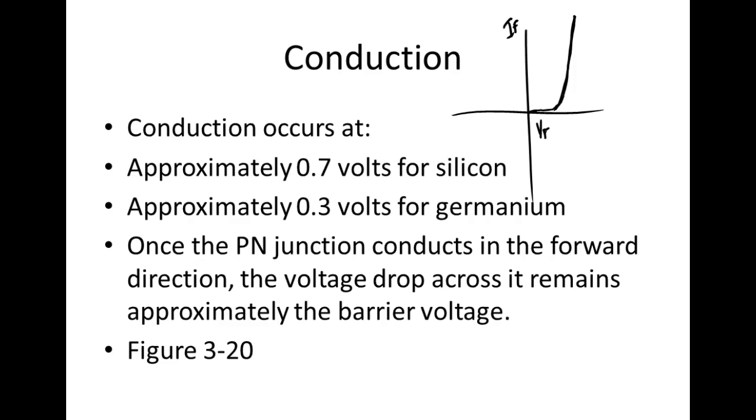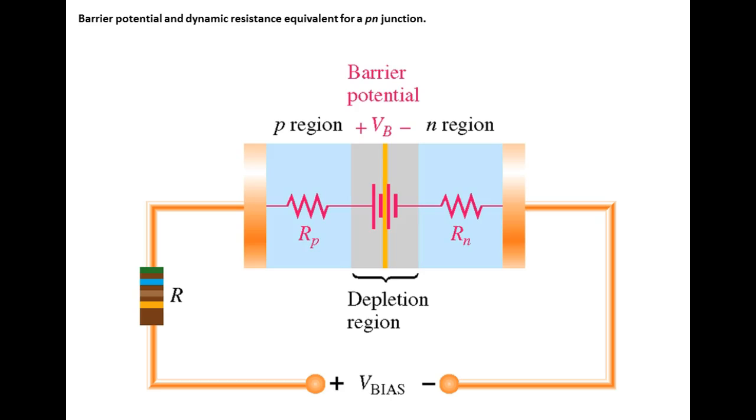If I put current through resistance, it's going to drop voltage. So this is basically what it looks like, these little old tiny resistors. The sum of the voltage drops would be the 0.7 plus the voltage these tiny resistors drop. And like I said, they're very, very small.